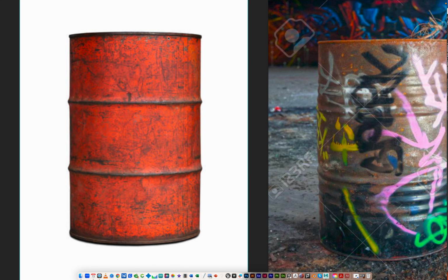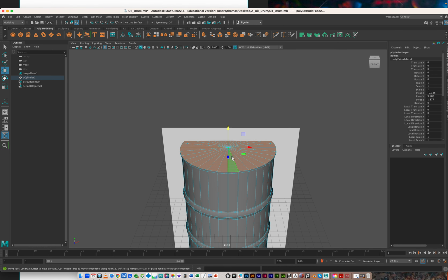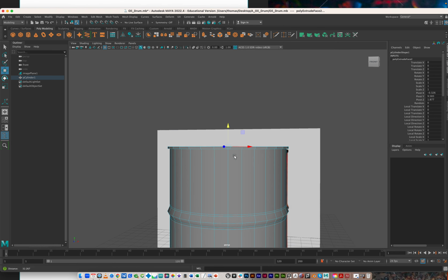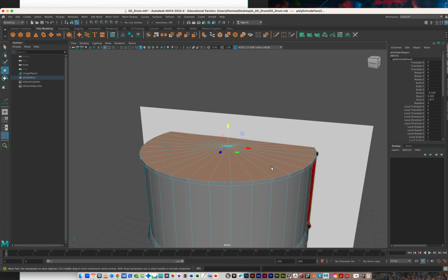All right, and all we're doing is making this ridge. All right, it's very, very small. We're probably overdoing it. No, it looks pretty good. All right, when I hit G again, hit R, and I'm going to squeeze it in. And you can see where it's starting to look faceted. So if we looked at this in a game engine, we could probably see that looks pretty bad. All right, so I'm going to not push this down. I'm going to hit G one more time, hit W, and I'll push this down.